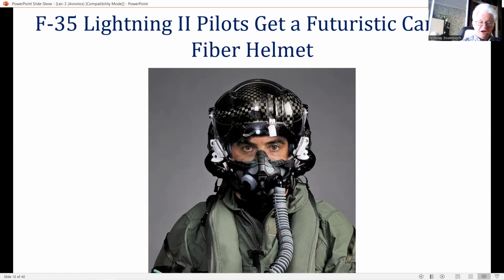Modern conventional aircrew helmets weigh about 1 kilo or 2.2 pounds, so the weight the pilot feels on his head during a 9-G turn is equal to 9 kilograms or 20 pounds approximately, and this is just acceptable.